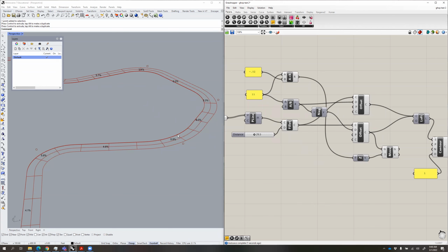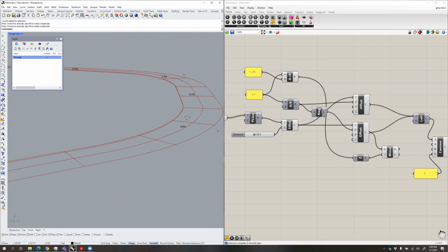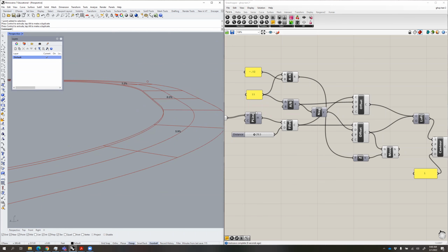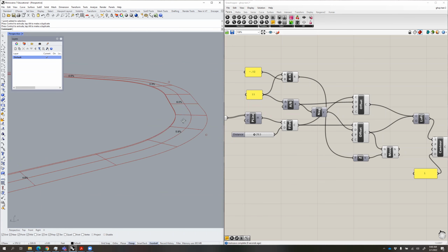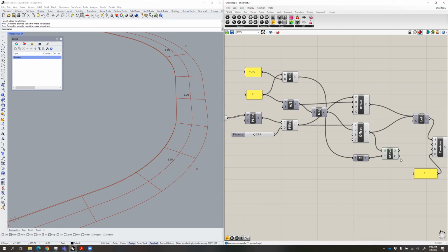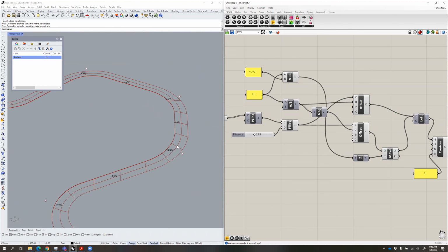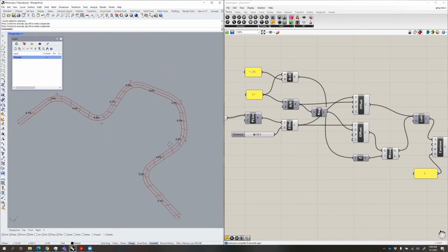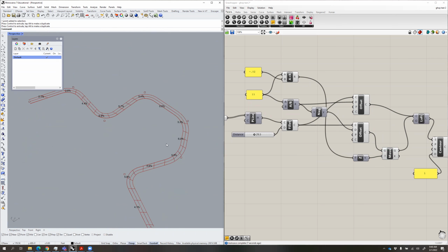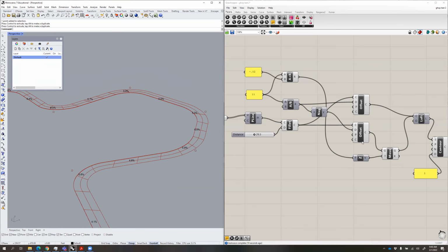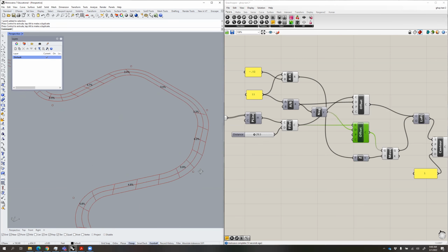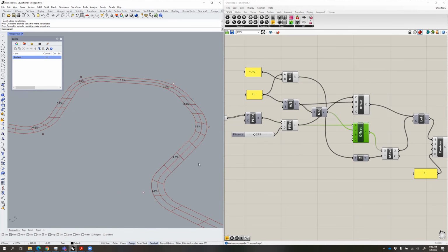So now that side here has moved down a dimension that creates a 2% cross slope. Now this curve here is the curve that we loft with that upper curve, which we didn't move at all. So this goes here, hold shift, move that in there. And now you have an appropriately graded walk, where it has the walk, but it has a cross slope associated with it.